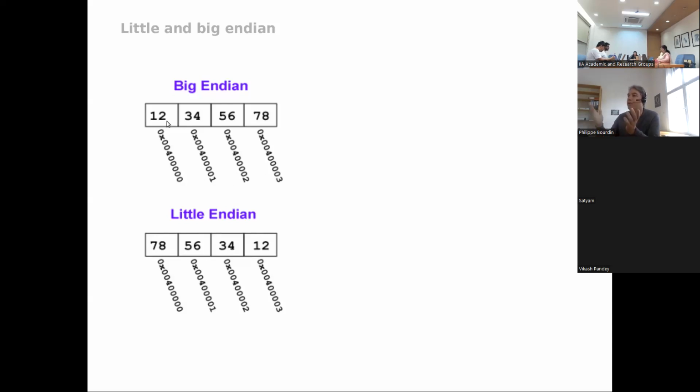So if you had a large number, like a 64-bit or 128-bit integer number or floating point number, whatever it might be, in the big endian case, the parts of that number are separated into the different cells the way you see here. So 1, 2 is in the first cell, 3, 4 is in the next cell, and so on. On the other hand, there are also so-called little endian types of processors, and these store the numbers in a different format.